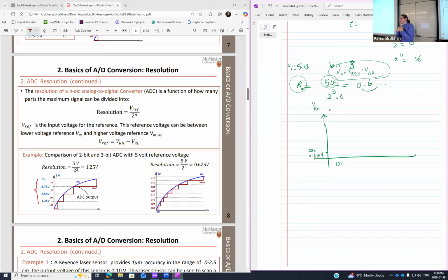All of them should be the same to figure out what resolution I want. Now make sense? Okay, voltage reference is the maximum number I'm going to start with to do the divisions. And that maximum number should be a number which is going to become closer to input voltage. Now, at some point, my maximum number should be 5 volts out of the VDAC.